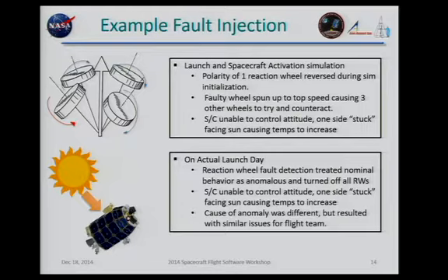We added a scale factor to the main thruster so that when they did the lunar orbit insertion, the orbit was a little bit off. So they needed to quickly come up with a correction orbit to make sure that you have a good moon orbit capture. So I think the key takeaway here is that building in that ability to inject faults to test flight software came really useful for training operators during pre-flight.